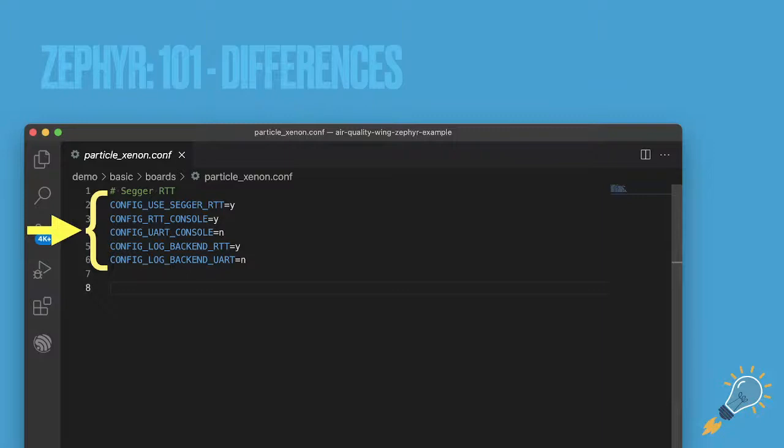If you find yourself using a constrained communication interface, maybe the only way you can connect to your board is with a JTAG connector, then RTT happens over JTAG, and this is specific to ARM chips. You can get a nice console over that. Very handy for very constrained boards, because then you don't need more pins or more debug connectors or anything like that.